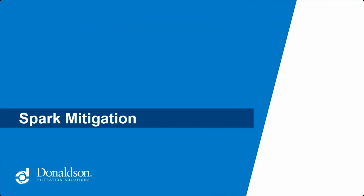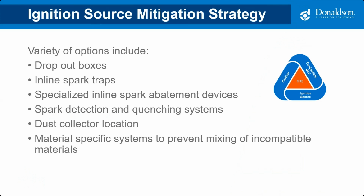All right, so moving on to our next topic, spark mitigation. Since lasers, as mentioned, will generate sparks on the application itself, I wanted to briefly talk about this topic. One method that we can use to help reduce fire risk is an ignition source mitigation strategy. A variety of options do exist, such as dropout boxes, inline spark traps, specialized inline spark abatement devices, spark detection and quenching systems, dust collector location, and material-specific systems to prevent mixing of incompatible materials.